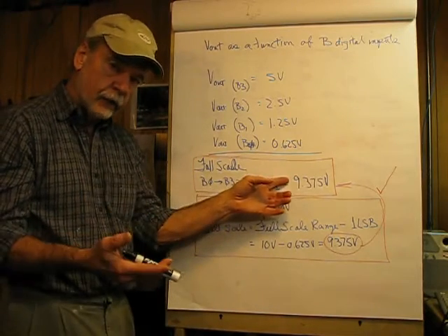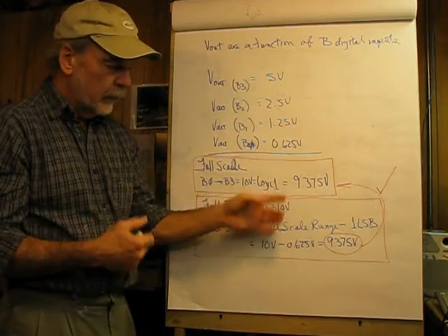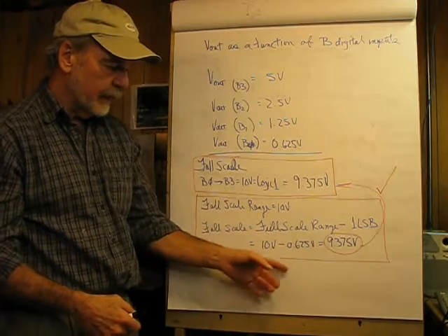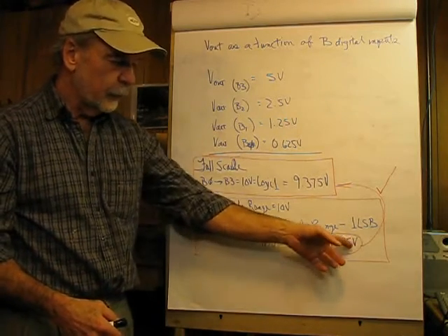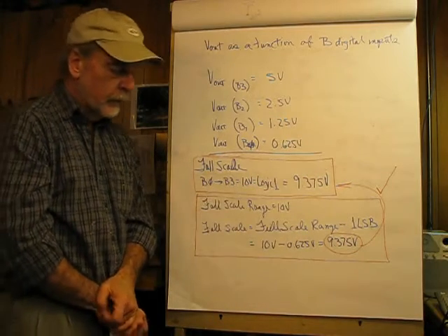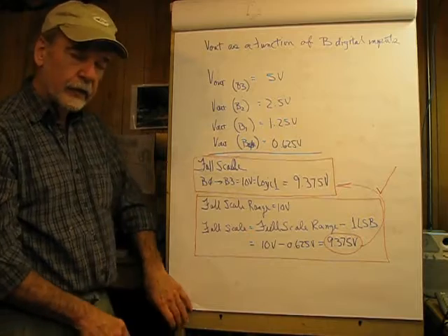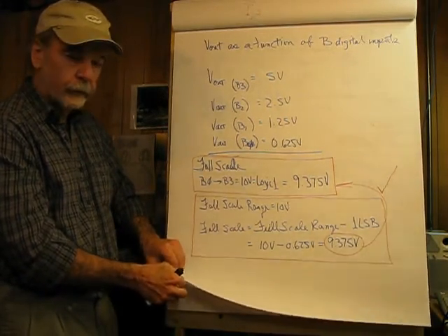It's as high as we can go with all of the inputs equal to 1, and is just going to be the full scale range minus 1 LSB, which again gives us 9.375 volts. So the R2R is very easy to implement in the manufacture of integrated circuits, and hence it's very, very popular.